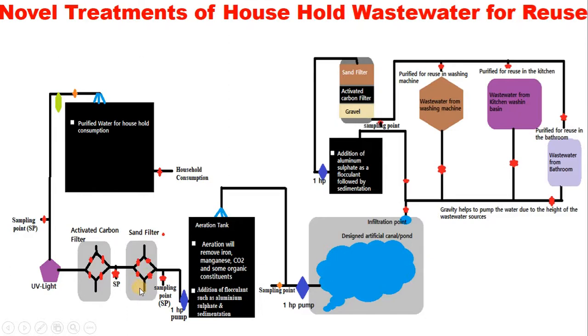How do you backwash? Remember, for normal flow, you close these two valves and open these two valves. But for backwashing, you will close these two valves and open these two valves. So instead of the water flowing this way, it will flow from down, stir the bed, and push the debris that will have been trapped here to come to this point.